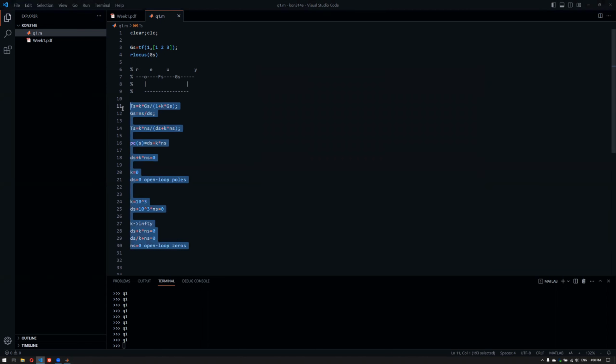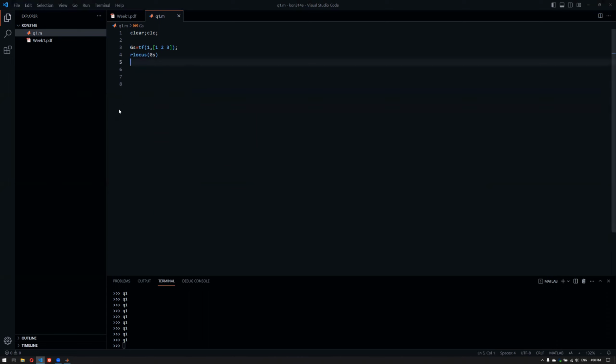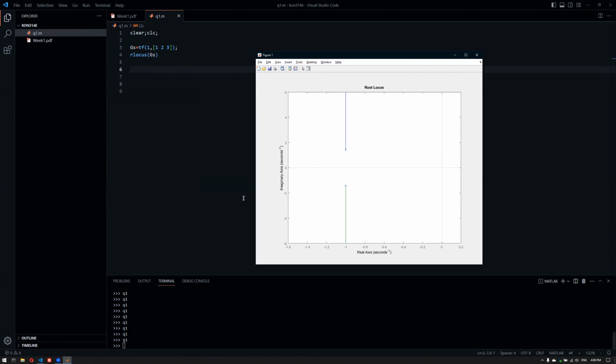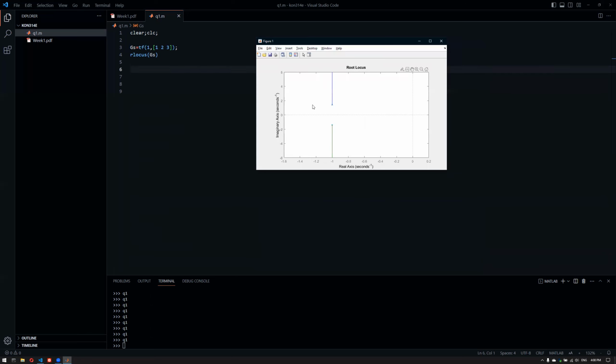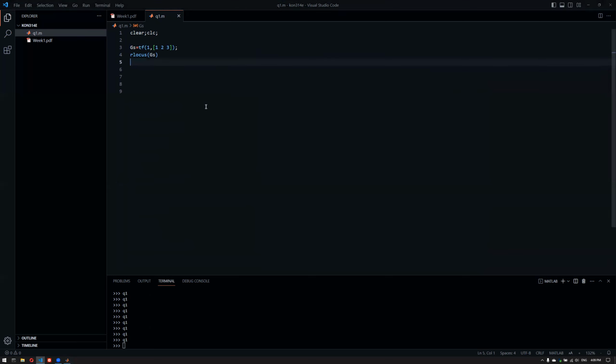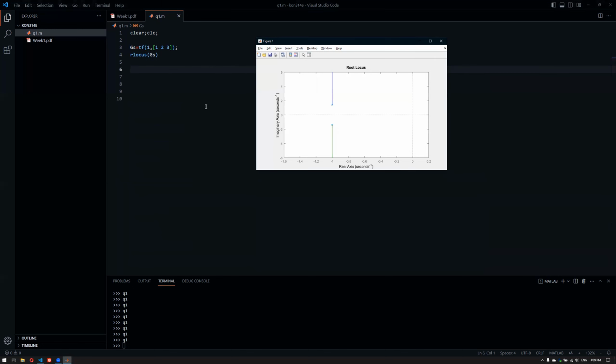Before we transition into creating a Root-locus plot, I can also look at this Root-locus plot here and make some assumptions about the resulting controllers and also the closed loops. For example, I can conclude that for this setup specifically, this system and a positive gain k, the settling time will not change. It will always be 4 seconds and it will be constant, no matter what the gain k is.